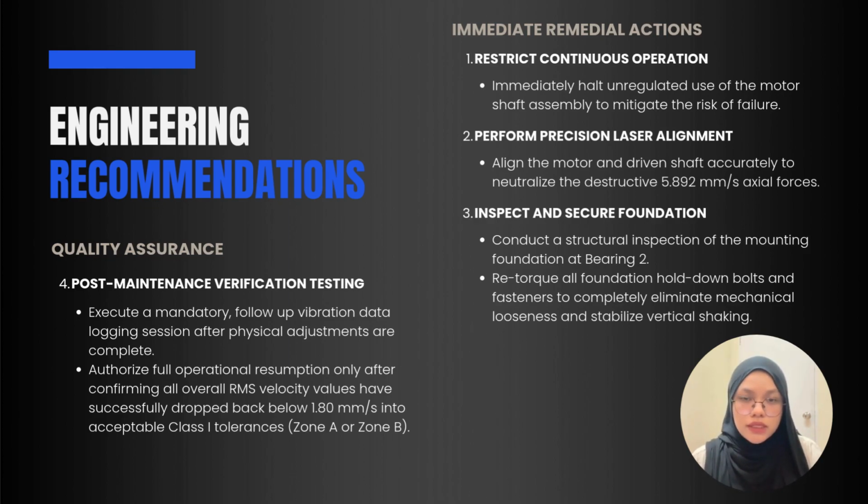And finally, as a quality assurance step, a mandatory post-maintenance verification test must be performed. Normal operations should only resume once a follow-up test confirms that all velocity values have dropped back below 1.80 mm per second, safely within acceptable Class 1 tolerance for Zone A and Zone B.